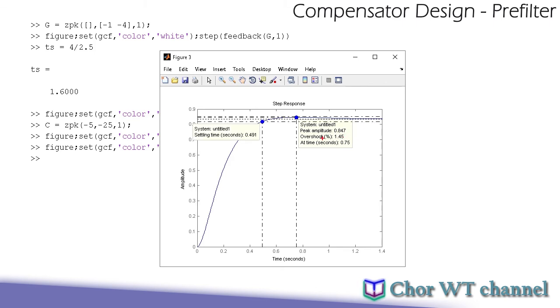Now you see that the output response, although it seems not bad, however, the overshoot, just now we have calculated, is approximately 0.111 as indicated in the root locus diagram, and also our settling time should be close to 0.8, although now it's actually better, but it is actually out of our expectations simply because of the existence of the zero.